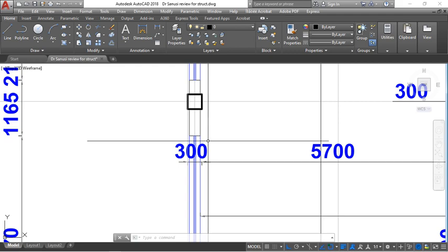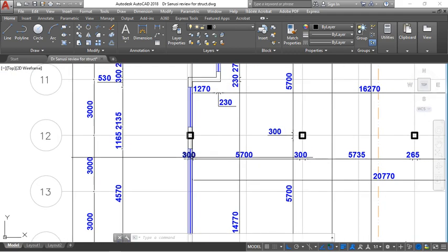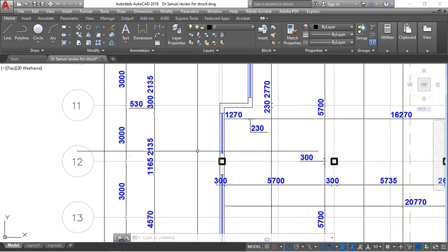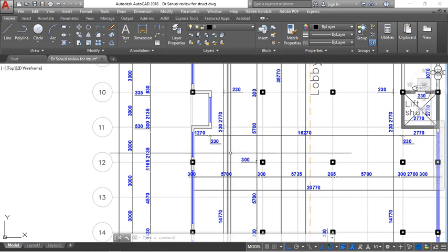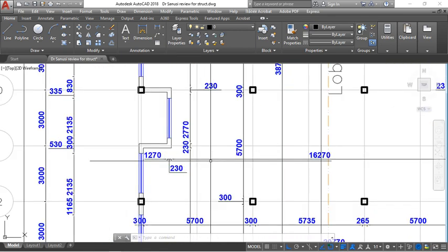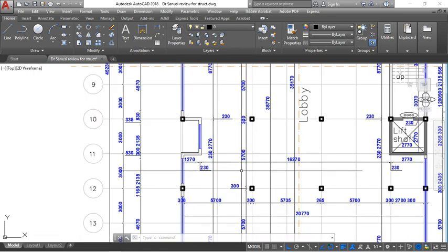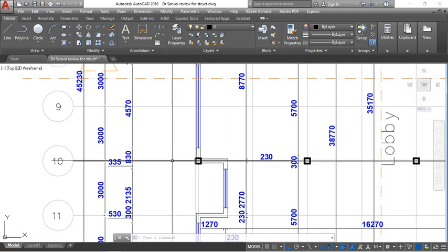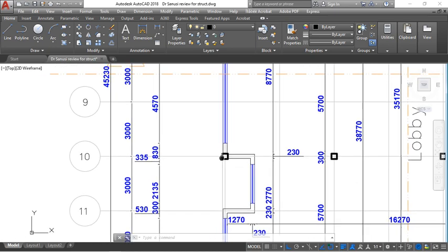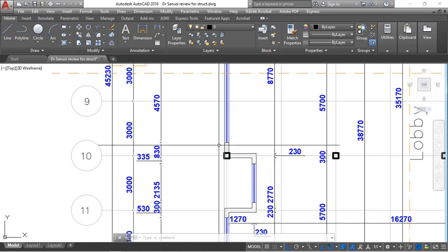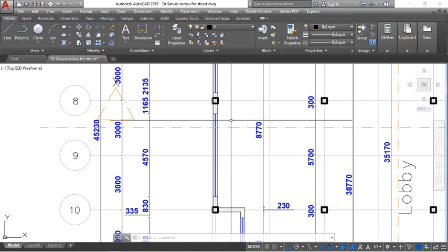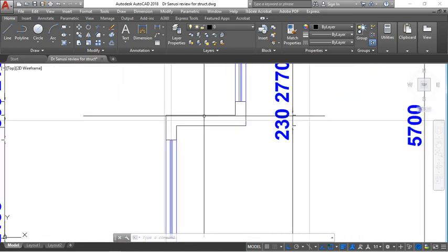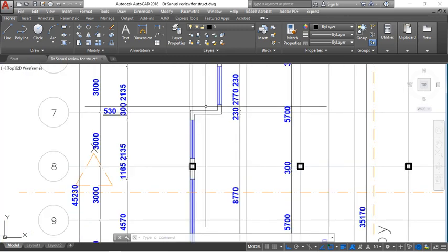So this thing has an effect on your structure. Now, given our terrain in this country, yes, we have places like Ikorodu, Songo, where the soil is very strong. So maybe if you have 150, 100, you can still be fine. But anything below that, 75, 50. I've seen 50. By the time I went to one side, one guy was telling me, I know one senior engineer, registered, who used to do 50, 75 mm.